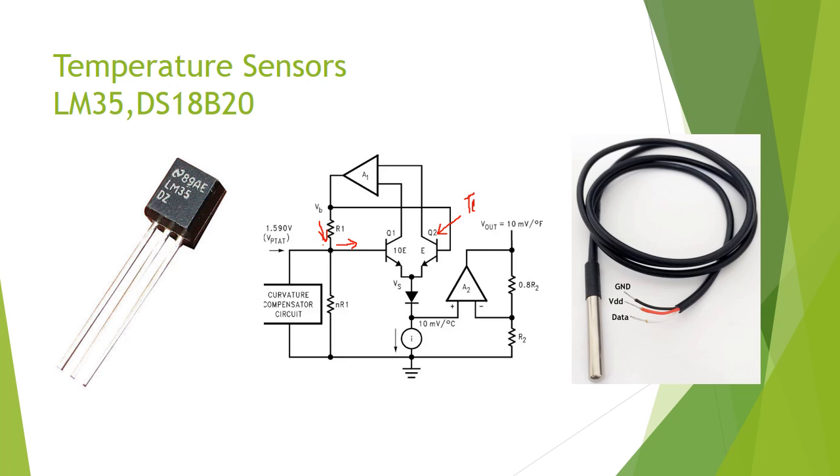What happens here is you are converting your temperature signal into a voltage signal, and that voltage signal can be measured here. Here you can see this is 10 millivolt per degree Celsius. So if there is a 1 degree change, there will be a difference of 10 millivolt.